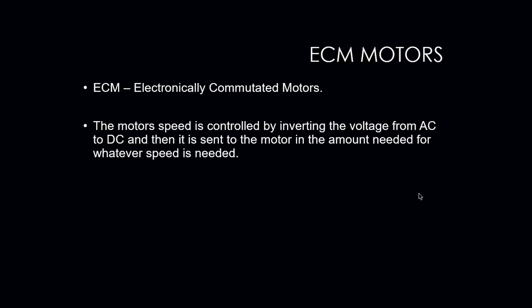You are then going to have the ECM module, as we call it, connected directly to the motor, and then some sort of circuit board that's going to communicate with the actual air handler itself. Then those three will communicate with each other to come up with the actual amount of air and speed that is needed to deliver to the space.